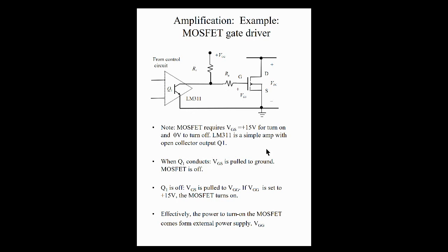So how does this work? We have our voltage here, let's say our source voltage at this point. When this transistor turns on, what is going to be the voltage at this point? This is a switch, right? The voltage across this switch would be 0 when it is on.